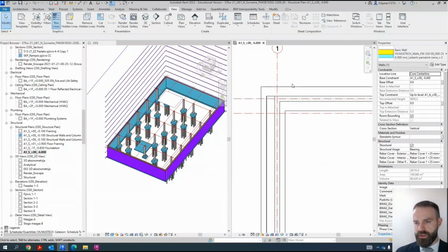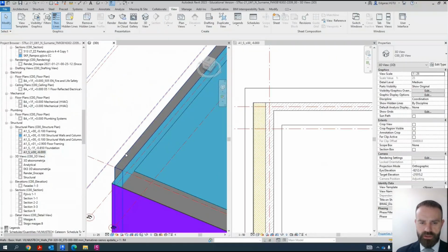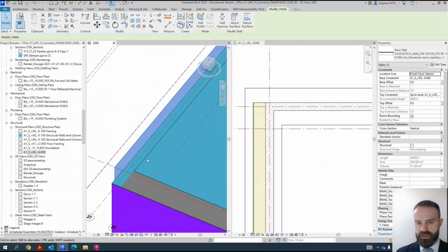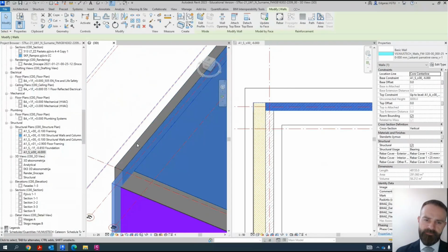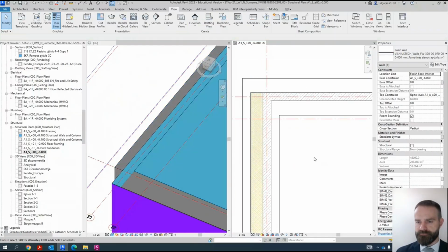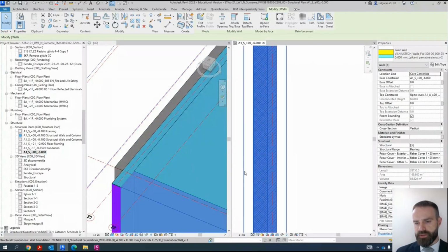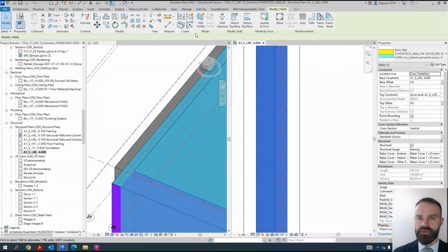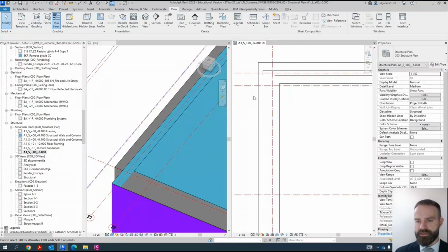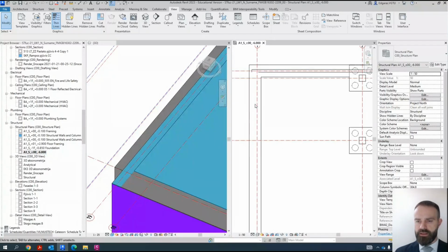And if you have a foundation wall from separate parts, like in here, this part represents the architecture part, and this part represents the structure part. In this case, I don't see any additional wall elements here. To eliminate all these architecture components, I recommend using a tool called Create Parts. In this case, the wall is divided into part objects, and it's now not visible in my project.